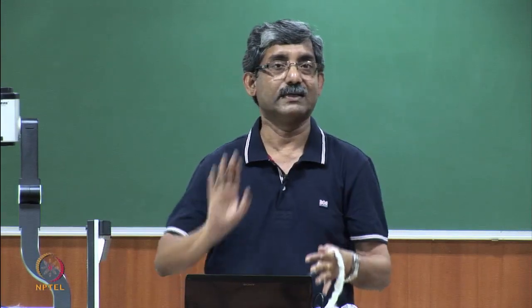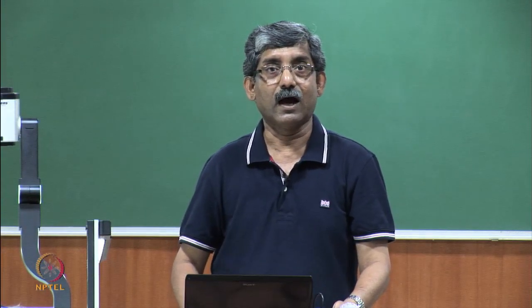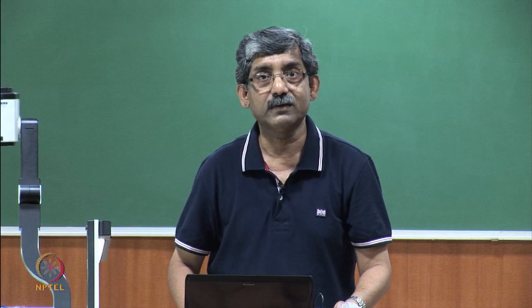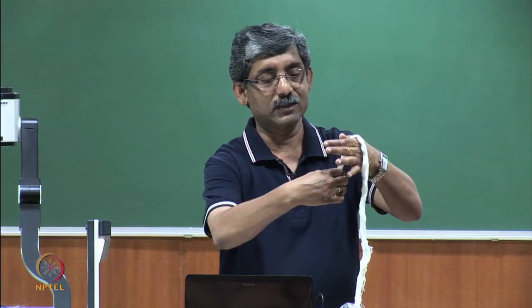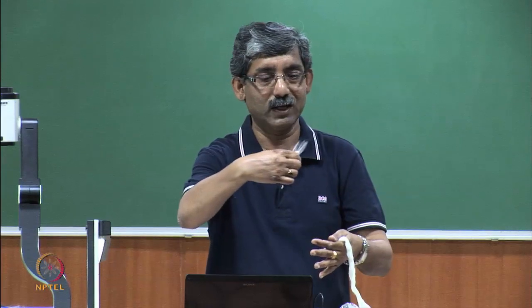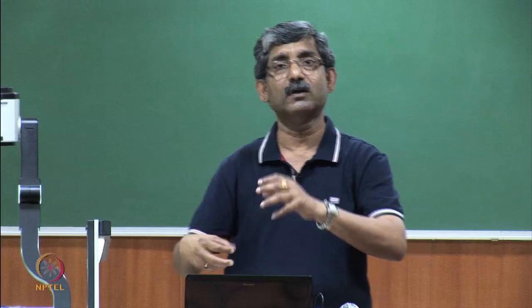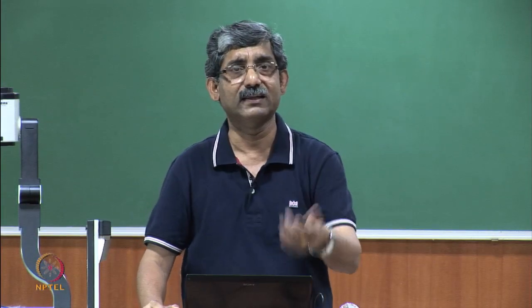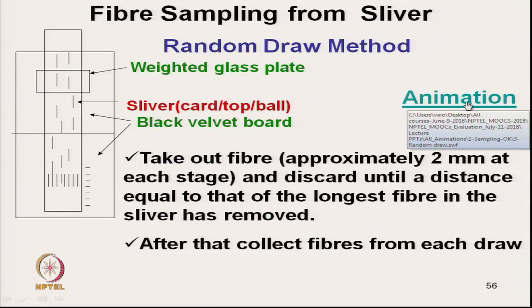keeping it for testing. This is called the random draw method, and after that we collect the fibers from each draw. Every removal is called one draw, okay? Then we keep the fibers, and these fibers will be used for different testing, like length, diameter, anything. Now, let us see the animation here.